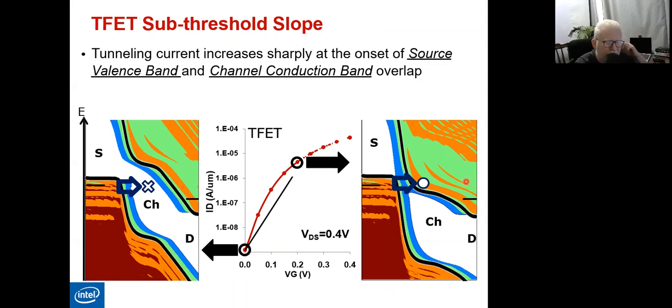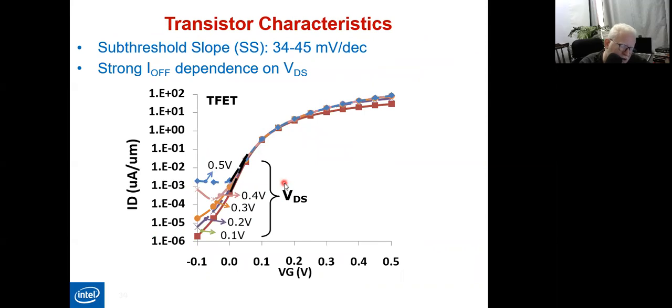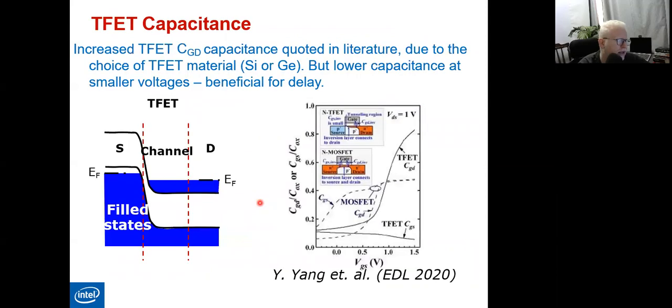Similarly here, the gate voltage acts just to narrow down the channel. But the main reason for the electrons to tunnel is to have an attraction force, a high electrical field coming from the drain. This can be demonstrated in this graph. So the higher the drain voltage, the higher the current you have. Okay, so this is simply the story.